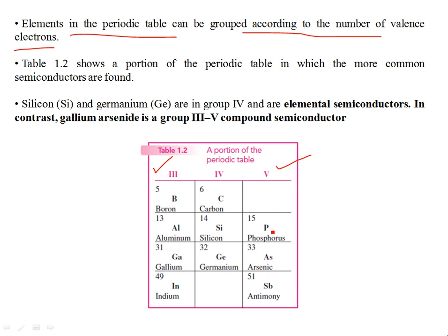For example, if phosphorus is introduced into the lattice of single crystal silicon, this phosphorus already has 5 valence electrons, and 1 valence electron is going to be contributed per atom of phosphorus. One mobile free charge electron is going to be present in the conduction band, which is going to improve the concentration of charge carriers and hence improve the conductivity of the material, right?